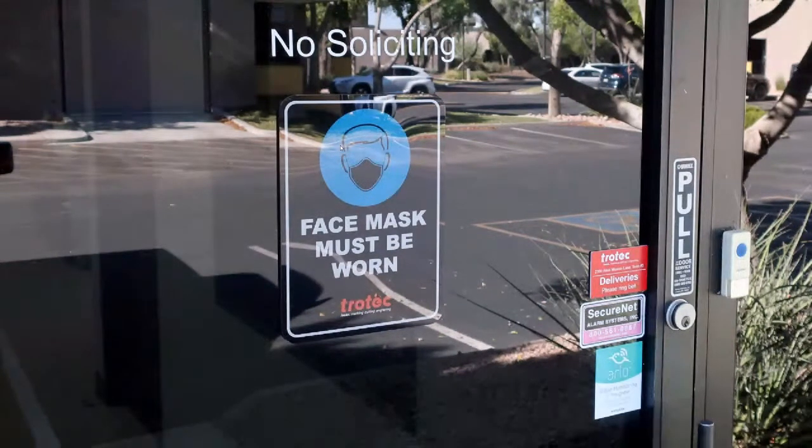And that is a great material because the reverse engravable stock like acrylic and the TroGlass Reverse plastic give you the ability to engrave away the back coating, whatever color choice that you pick, and then take it out of focus and engrave it again, which makes it a little more transparent so that the paint goes through a little better. Then apply the paint to those pockets and then flip it over for that finished, high contrast, multicolor, UV stable, diverse, very shiny, polished looking sign.